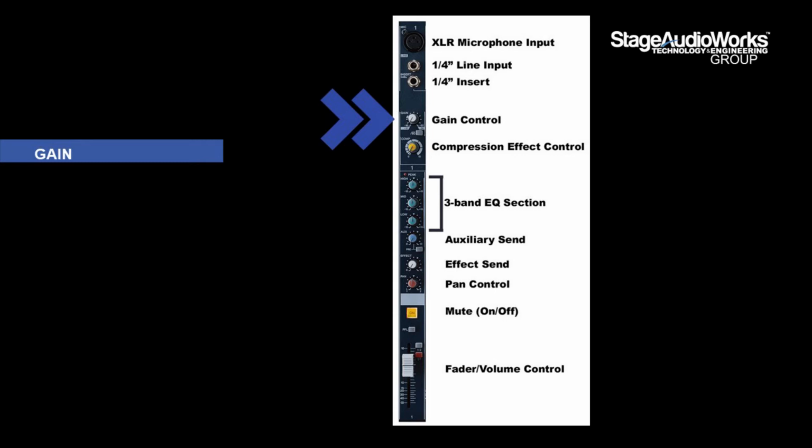What this does is ensure that no single input controls the amount of headroom that you will have available. So you'll need to go through each input channel one by one and adjust the gain for the preamp stage so that you aren't getting too little or too much signal into your console. A good practice is to solo the channel, the PFL, and adjust the gain until you get a reading of around 0 dB on your incoming signal.